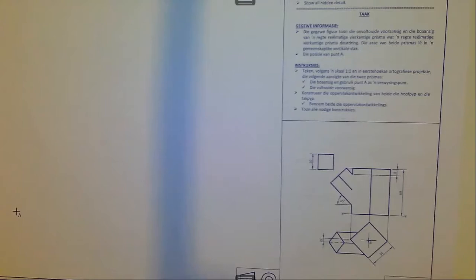Right, the complete front view. When they talk about the complete front view, if you check, there are certain lines which have not been drawn. So what we require is to come up with the line of intersection, since this is a straight-sided shape. When we are looking at the top, this is basically the line of connection between this one, which we refer to as the branch pipe, and this one, which we refer to as the main pipe. So on the top view, the line of connection is already there, which we refer to as the line of intersection, okay? But we also need now to establish the line of intersection with regards to the front view.